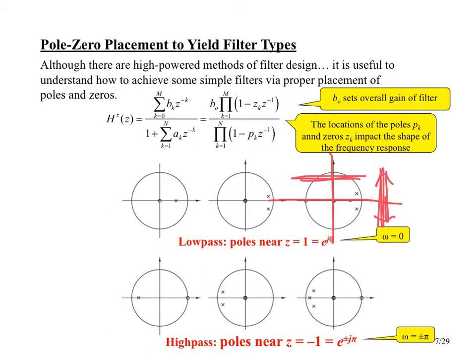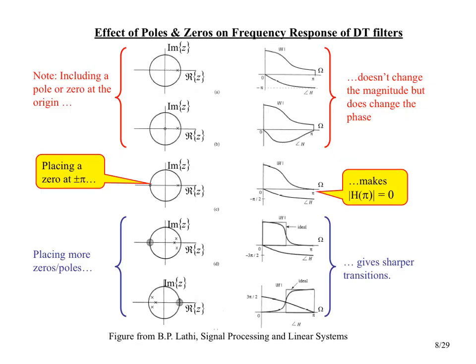So we'll leave it at that for now, just alluding to this idea that once we have a low-pass design, we can transform it into a high-pass design by just everywhere there's a z, replacing that z by -z, and we will automatically transform low-pass into high-pass. And no surprise, if we started with a high-pass and we replaced the z in that by -z, we would transform it into a low-pass. So that's a low-pass to high-pass transformation, and we'll talk more about that in just a bit. We've seen this slide already, just thought it would be a good idea to revisit it.